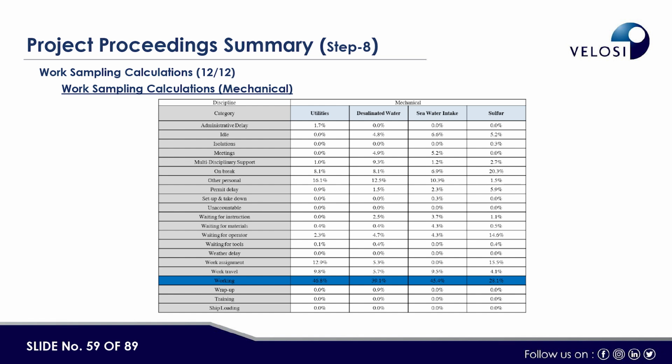So if I try to bring it to the point, if a preventive work order is issued for a pump or for any other equipment, and if a month later the corrective work order is coming, either the PM was not done or the PM was ineffective. Otherwise, why does the corrective work order have to be issued one month after the preventive maintenance?